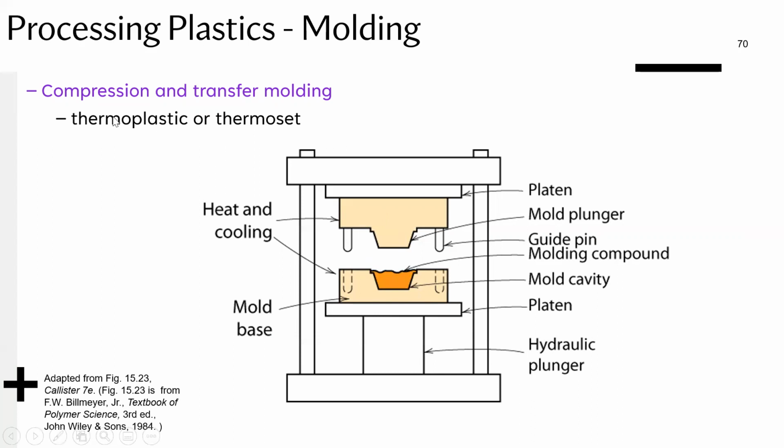And you can note here that it's not just thermoplastics, it's also thermosets. And this might confuse you a little bit. Well, I have to say, thermosets have two states, before they've been cross-linked and after. Here, it's before. So you haven't actually produced a material. You haven't produced an object out of this material. You've got the thermoset base material, which is a monomer.